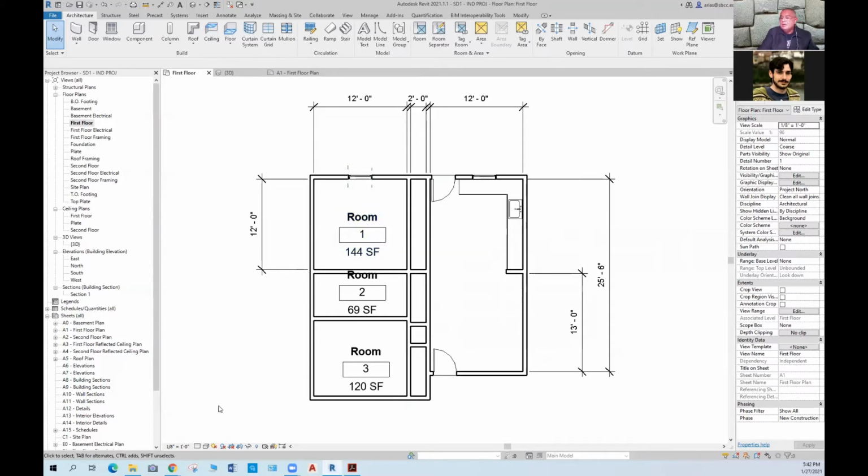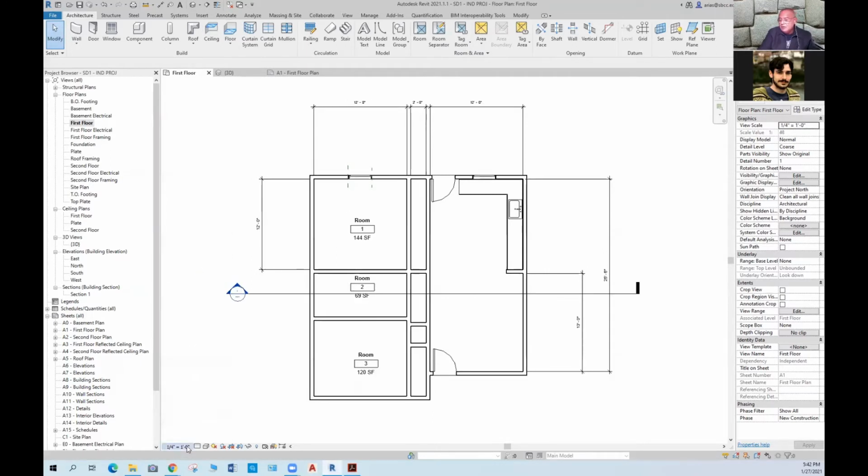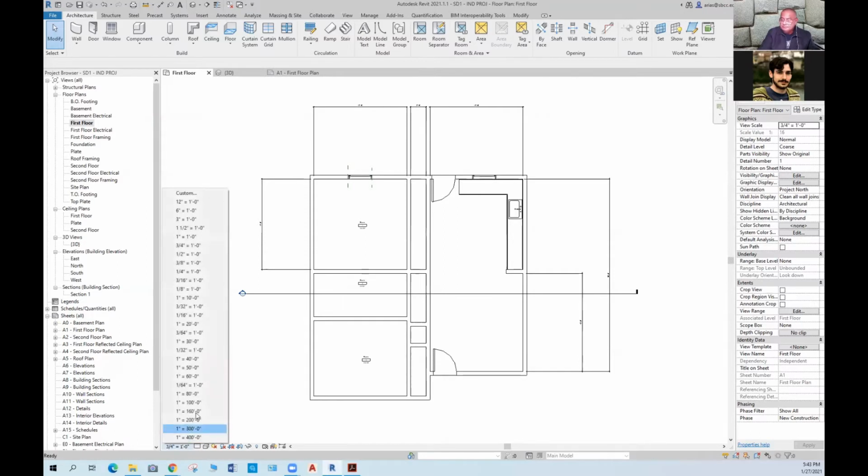And that's the program automatically setting up the annotations to be the right size, similar to what we do in AutoCAD with the annotative scale feature. So if I change that to 1/4, then it goes back to that. And if I do an even larger scale, like 3/4, then the text looks really, really small. But remember, the text is not changing size. What changes size is the zoom factor on the building. The text remains the same height.